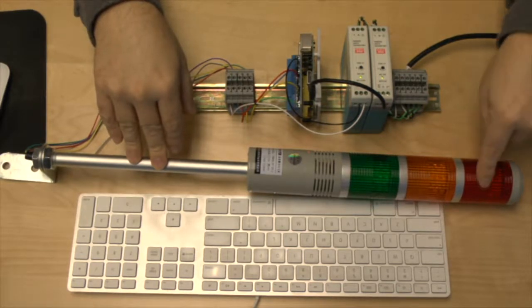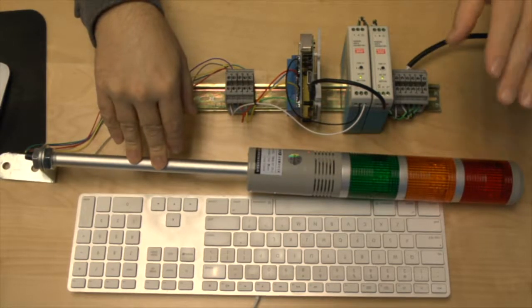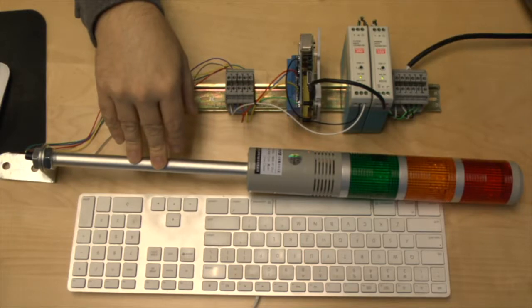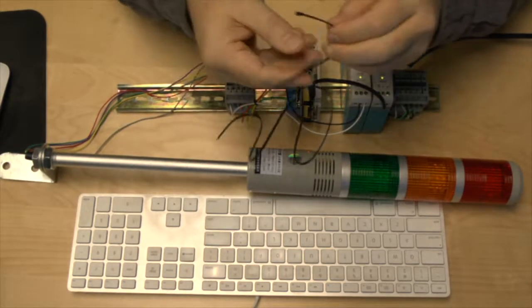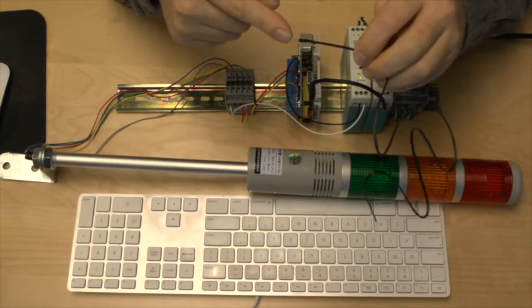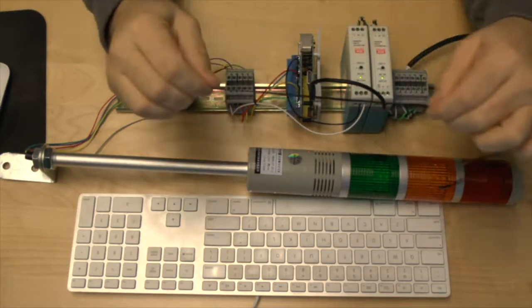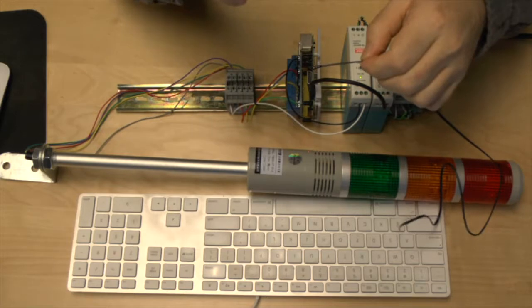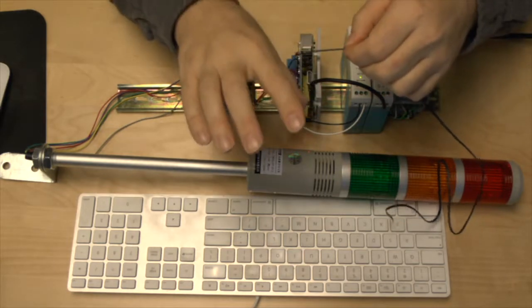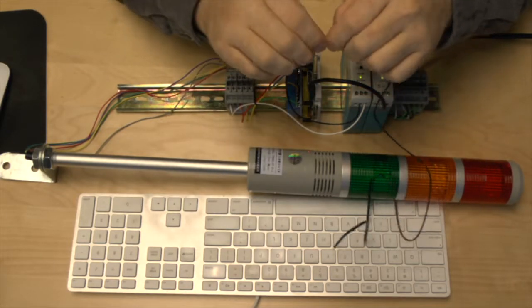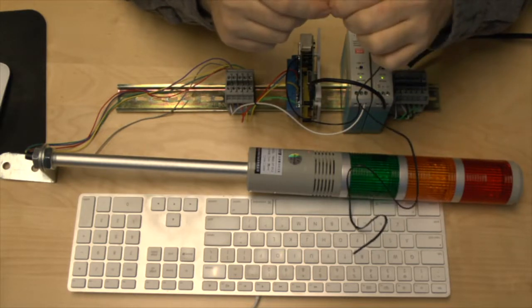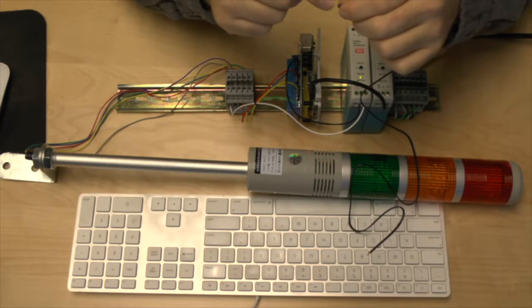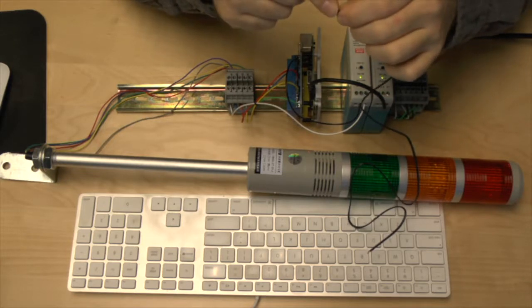We have other versions that are set up as sensor nodes. So, for example, this is $7. This is a digital thermometer, and we can tape this to an electric motor that runs an auger or a heater on an extruder. And in the case of an electric motor, we can monitor the temperature of the motor and notify Sabe when that motor is getting too hot.